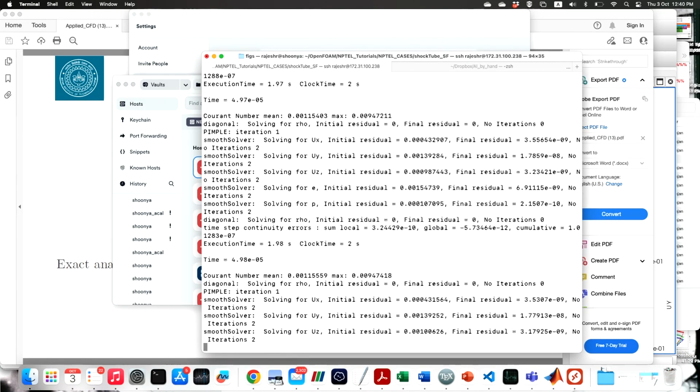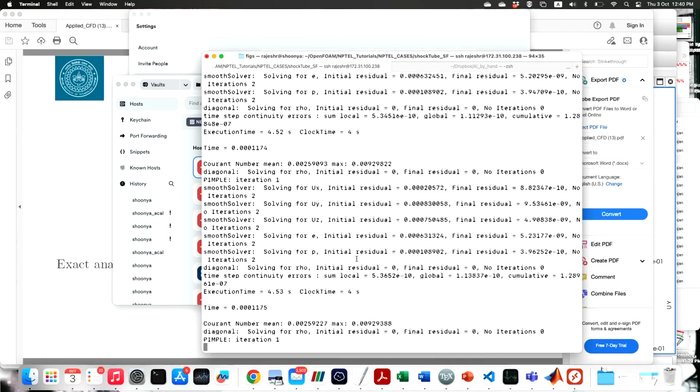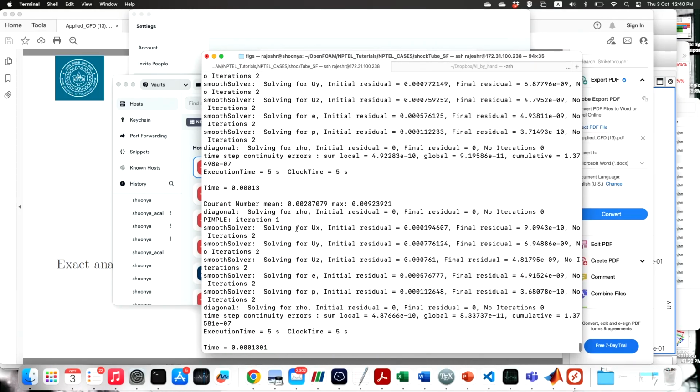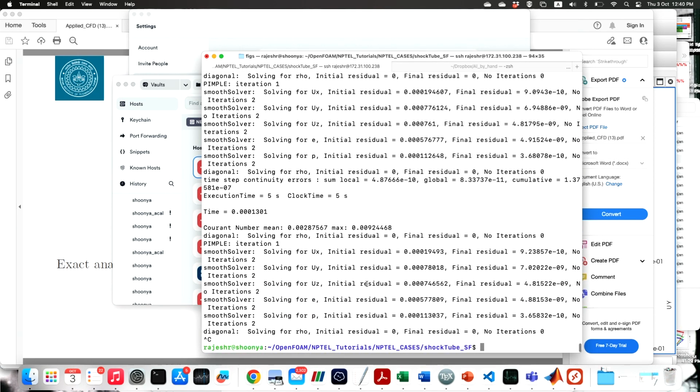Okay. So, now it is solving, and I will show you later, or maybe I just stop and show here that now you can see that it is solving for ux, uy, uz, energy and pressure, right. So, it depends on what kind of solver you use, whether it is pressure based or density based. In the pressure based also you can have the energy equation, right. So, that way it can solve either for pressure or some other quantity, right. You need 5 equations, right. So, here it is solving 3 momentum and enthalpy, and finally it is solving for pressure.